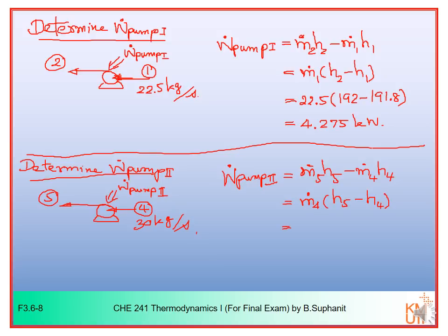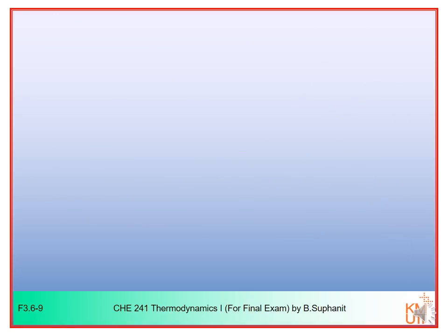You know everything: 30 kilogram per second for M4. H5 is provided by the problem, 318.53, minus H4. H4 is at what? We have to determine H4 first. We don't know H4. Now we have a problem here. So you have to determine H4 first, in order to calculate the work for the second pump. Now, how do we calculate that? We can determine H4 by doing the energy balance around the mixing point.